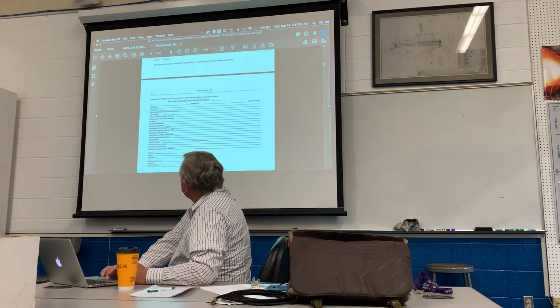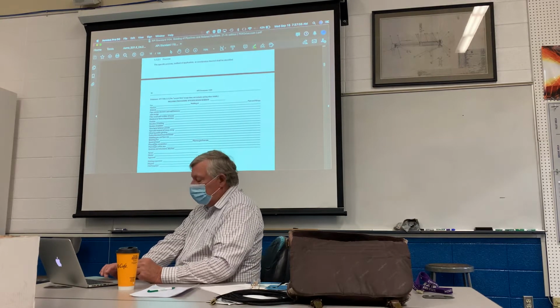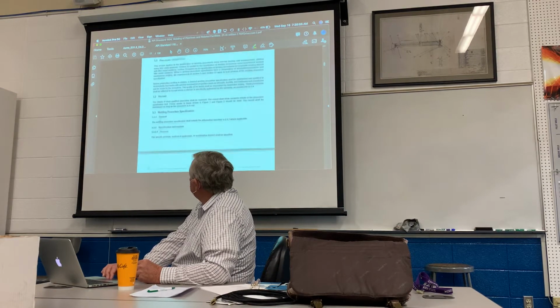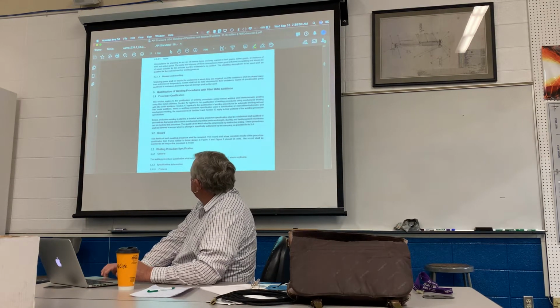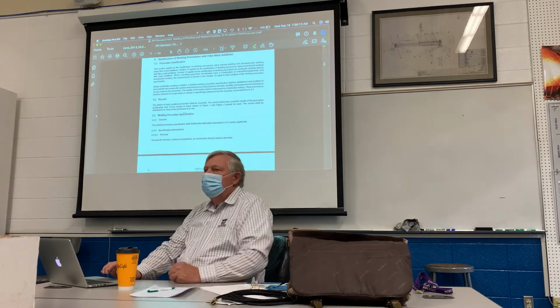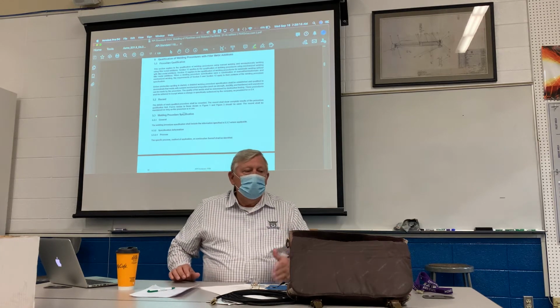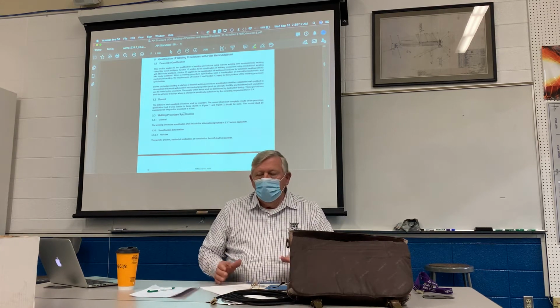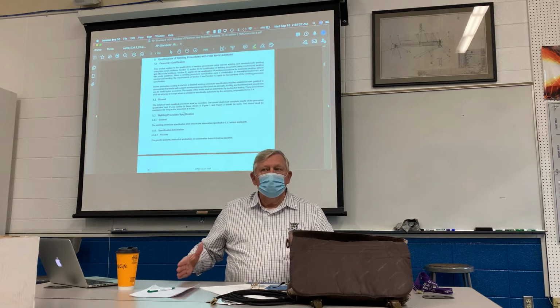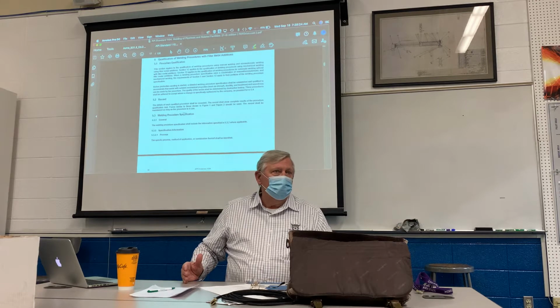Every line that has something listed here, process, material, pipe outside diameter, joint design, filler metal, all of these listed here are also found in the document beginning right here, 5.3. So any of the data, any explanation of what is wanted there, will be found in that code book beginning at 5.3.